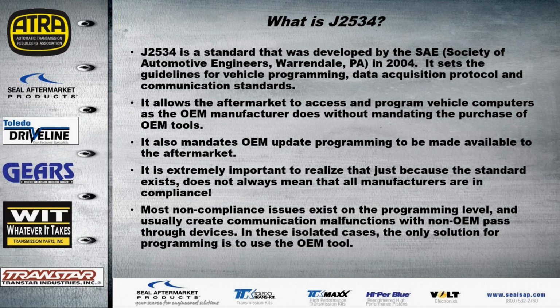And again, the J2534 standard covers specifically ECM, PCM, and TCM programming only. Even though there may be some aftermarket suppliers that allow other module programming, the J2534 standard allows for support only for drivetrain related modules.